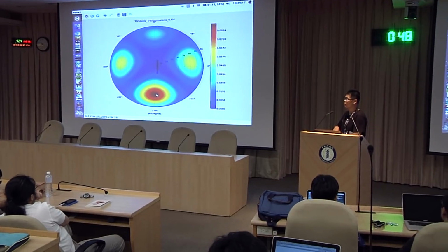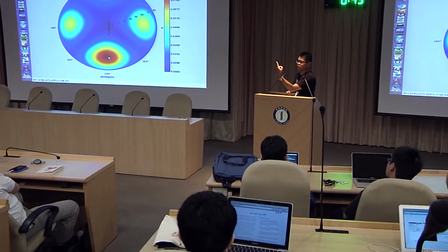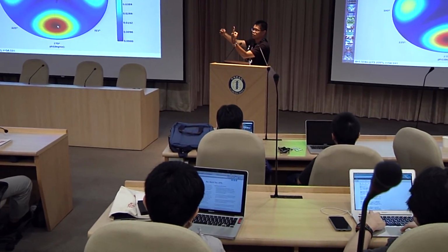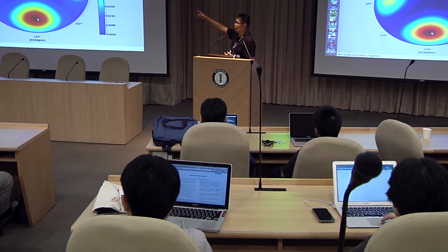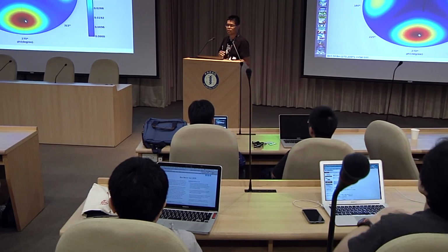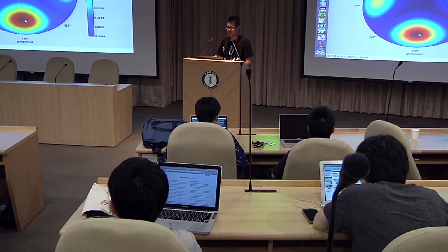Because of birefringence, the liquid crystal direction is fixed in this layer, but you are looking from a different angle, so you see different phase retardation. And at some other angles, the light will leak from this display, so you see very bad image quality in this operation mode.